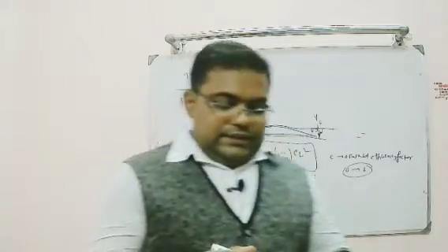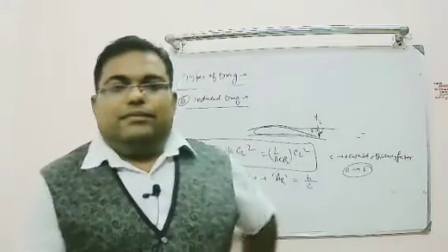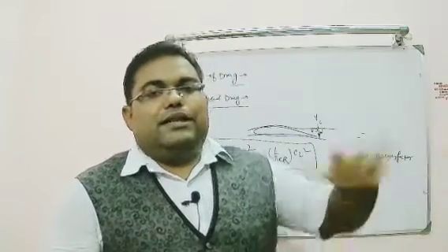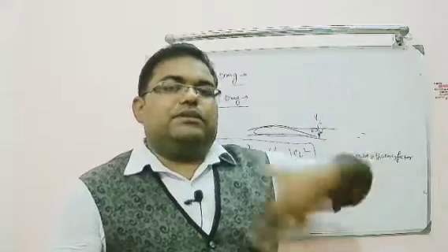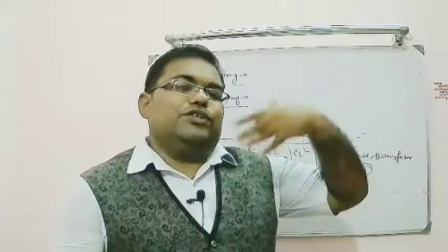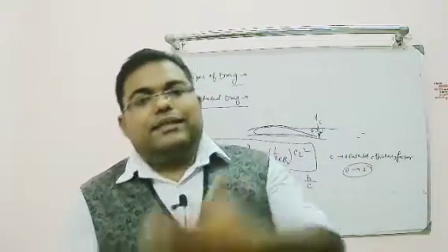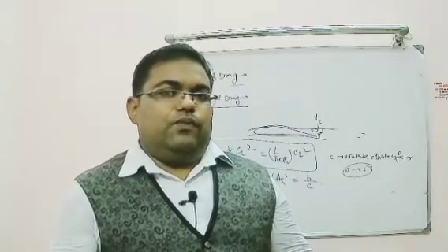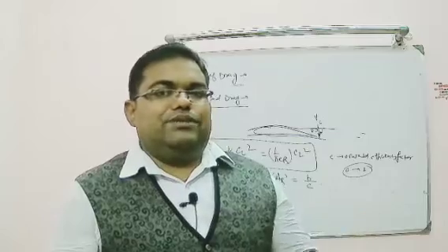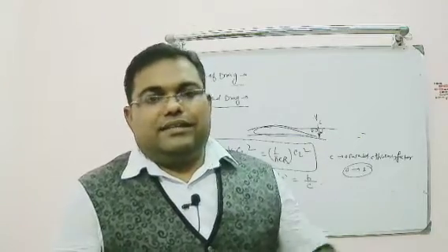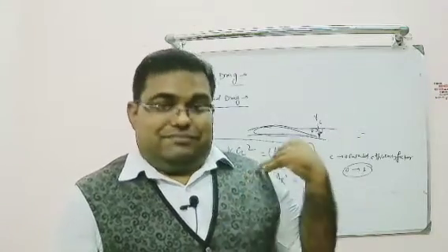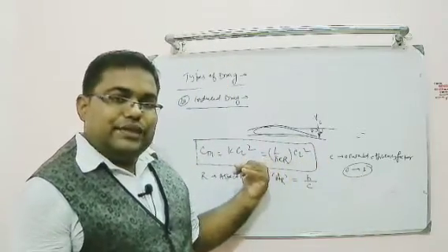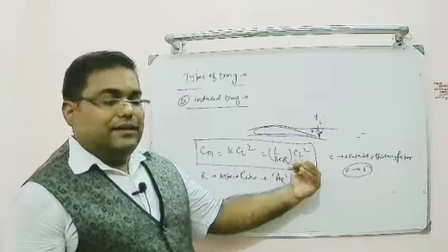So how are vortices produced basically? Vortices are the result of lift. When lift is generated due to the circulation, and the circulatory flow comes to the trailing edge and separates, it generates the tip vortices. So induced drag is the cost of generating the lift. We have generated the lift, because of that trailing edge vortices form, and those trailing edge vortices will induce the drag. So drag due to lift is known as induced drag. That's why the CL term is there.